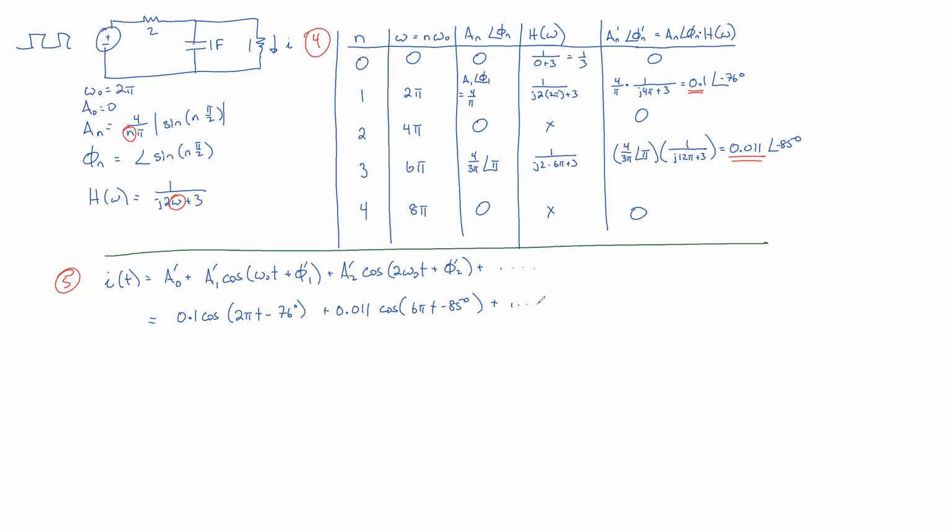And how many parts would you have to add? That's a judgment call. But seeing as how your magnitudes are dropping off by about a factor of 10 each time, I mean, your original waveform varied between -1 to +1. Your first part that's passed is 1/10 of that. Your next part that's passed is 100th of that. I would guess your next harmonic that you'd have would be on the order of 1,000th of that. And so if you're not worried about millivolts, you could stop there. And that's it. That's the secret of how to do this.